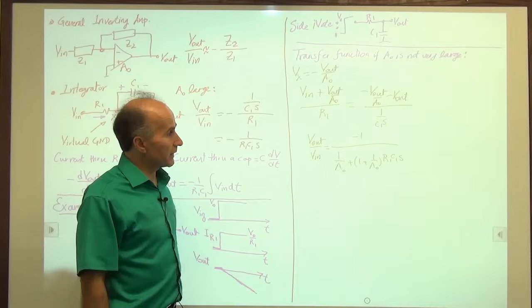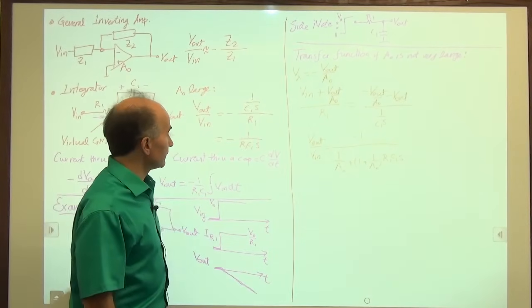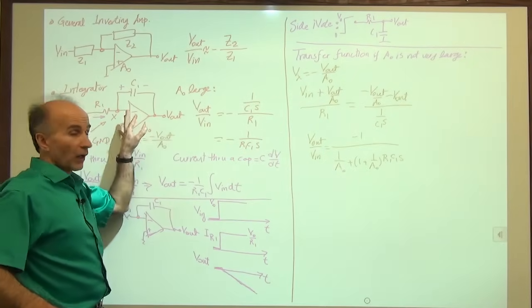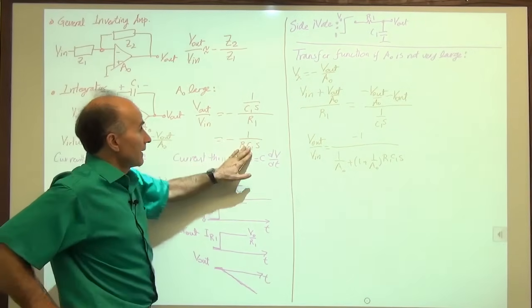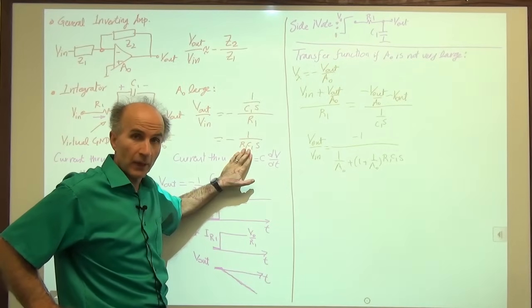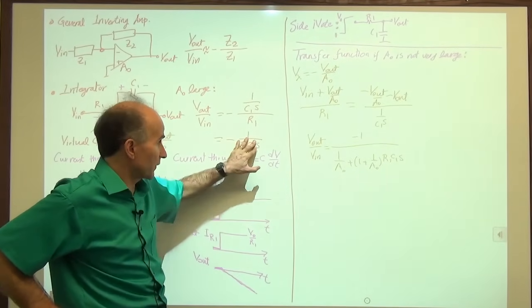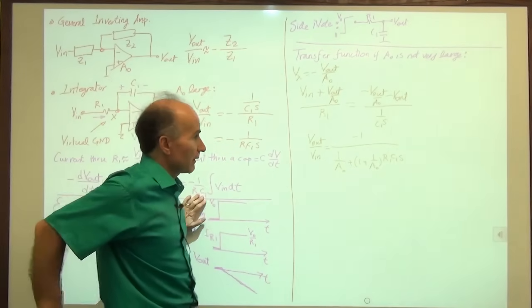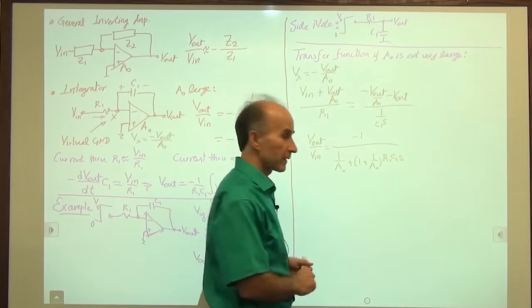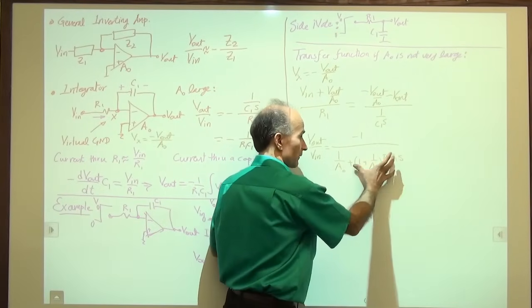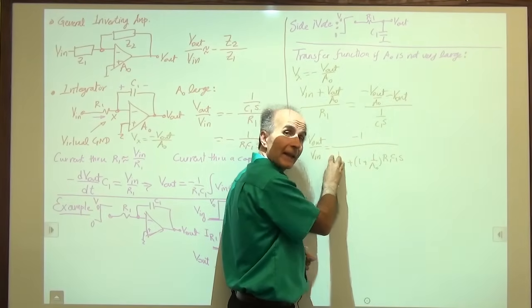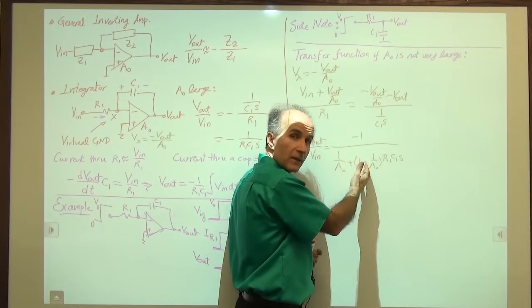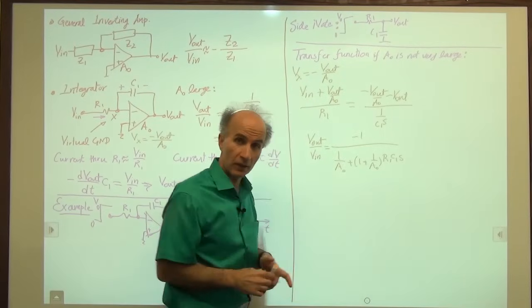All right, so what's interesting is the following. With an ideal high gain op amp, this is an integrator. And we know that because if you take the Laplace transform of this, we get this. But here it's not quite that, because we have S with a coefficient, but then we have something added to it. So yes, this is a pole that is no longer at the origin.